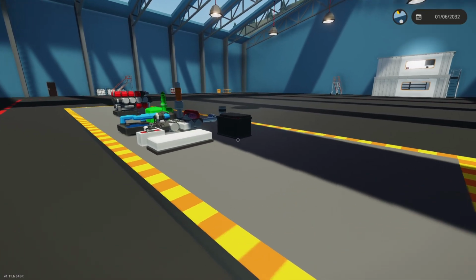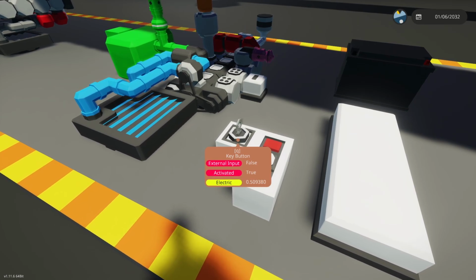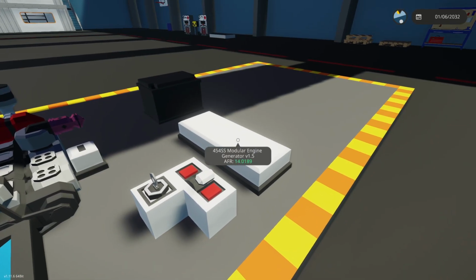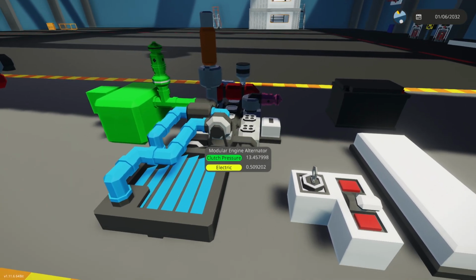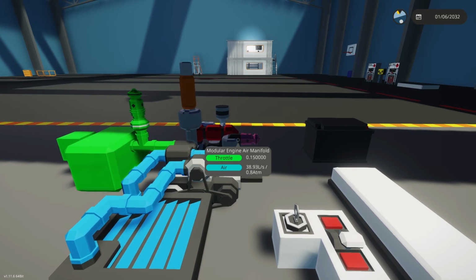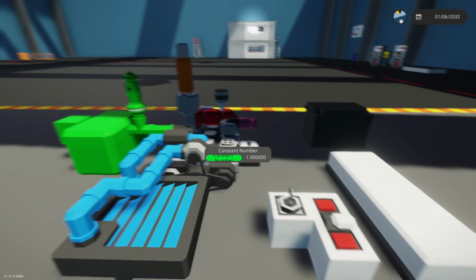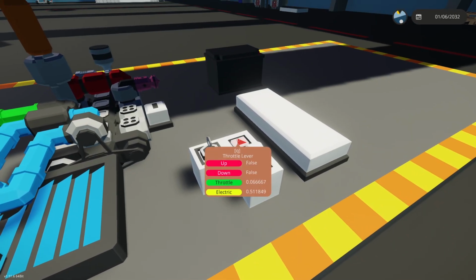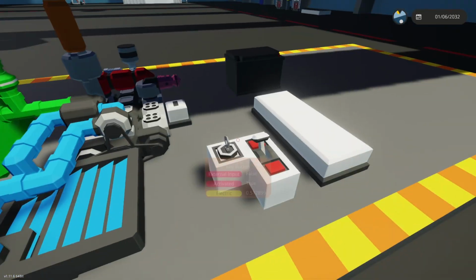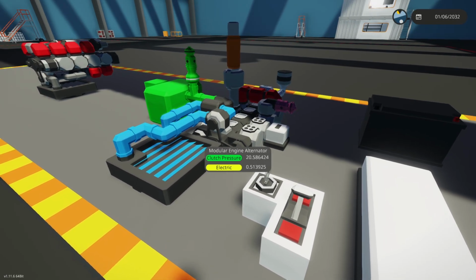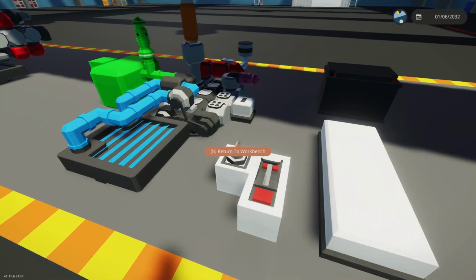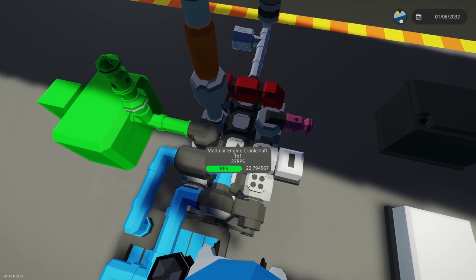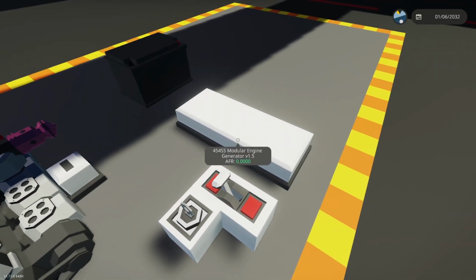We'll take a look and throttle it up. Well, first let's start it on. Now that is way too long for that starter, but it's okay. It seems to be chugging along quite nicely, even though this is 0. That's because we've set the throttle on the generator microcontroller. And if we turn it up, it revs up, and you can see that it does not want to exceed that RPS that we've set the limit to. So as soon as it goes over 20, it kind of down throttles itself.